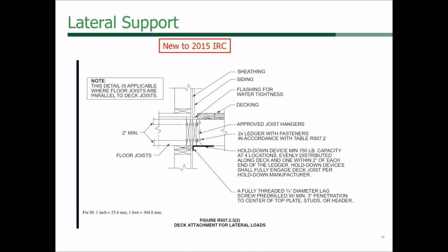You don't have to rip up the ceiling if it's an existing condition, and all those situations. The problem is that whether this is compatible or works as well as the 2 heavy 1500 hold-down tension devices isn't really known. It was never really shown.